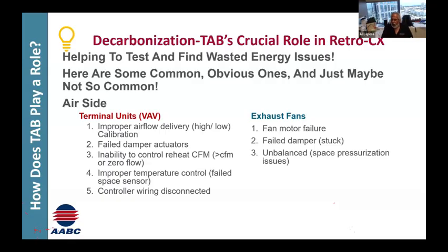I go, yeah, you are. When I tell an owner, auto calibration means that the box, when it wakes up in the morning, goes to 100% open and says, hi, I'm 100% open. And then it goes to 100% closed and acknowledges the same thing. It doesn't say how much airflow it is. That's just by a signal to the actuator. That's not actual proof, and it ends up with a number on the screen. You don't know if it's true or not.